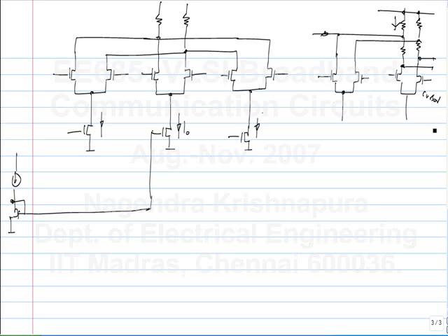But then I want a number of different weights. What do I do? How will we vary the resistance? Yeah, one possibility is to have a MOS transistor, but then somehow you will have to vary. Firstly, the MOS transistor is not linear. That is one problem, because now you are passing the output of a linear equalizer through a nonlinear element, and that will introduce some distortions. So that is not necessarily allowed.